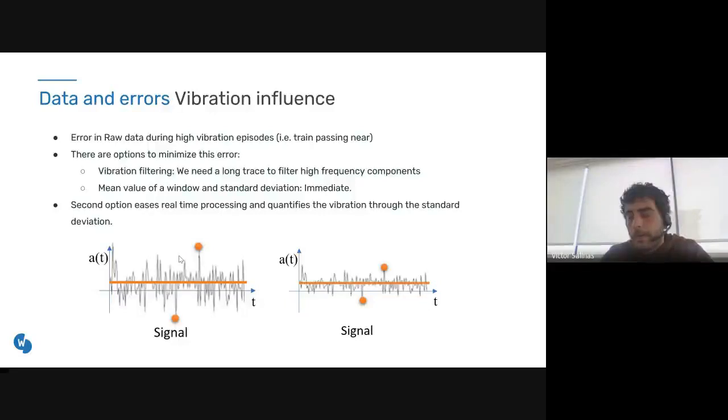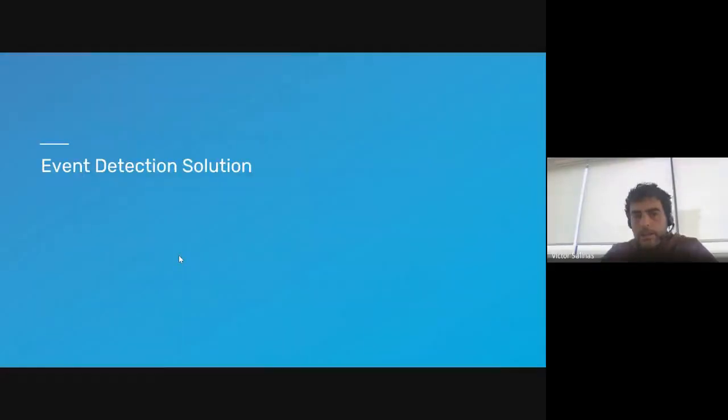You can see that depending on the exact point you pick up the sample, it can be different. But on the left, that is a high vibration environment, this difference is bigger. So a good understanding on this is to capture the mean of several samples and consider the standard deviation to understand this effect. And this is all regarding the tilt meter and its principles and transducing.